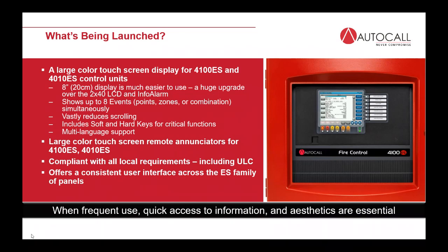This is also compliant with all local requirements, including ULC. So those of you that are in Canada are familiar with the requirement that the ULC standard has that says you have to be capable of displaying 8 zones of alarm simultaneously.